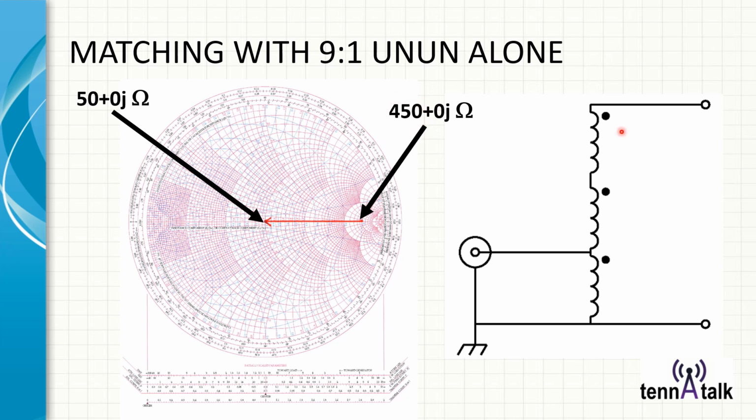50 ohms. And as you may recall from podcast 3, a 3-to-1 ratio, 1, 2, 3 turns on the antenna side, and that's the input to the system. Okay, that's our starting point, always on the antenna side on the Smith chart. Just remember that. To a single coil here into the output to our, let's say, PL259 or BNC connector to the radio or to the coax. And so that's what will take us from 450 ohms straight to 50 ohms very, very nicely.